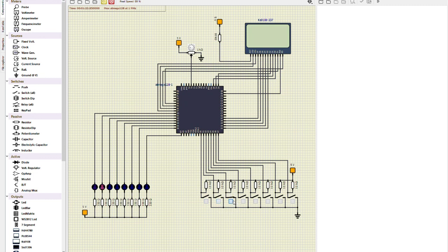As soon as we have lights on and ignition off, we can see that the lamp at port B, pin 1, starts to light. It's our general case. And it doesn't matter whether we open the door or close it, the light is still on. The only thing which can affect this is some other ports. So we filter them out with the help of our XOR operator again, and our wildcard rule works just fine.